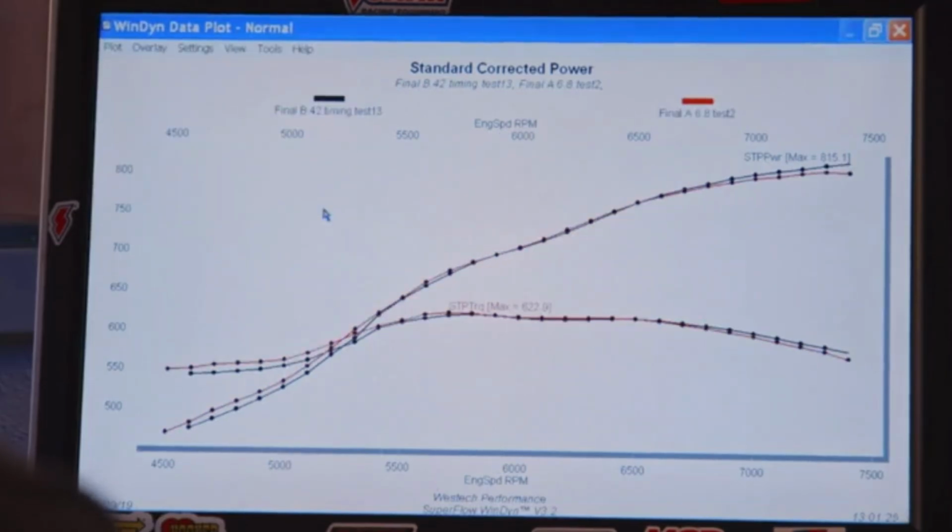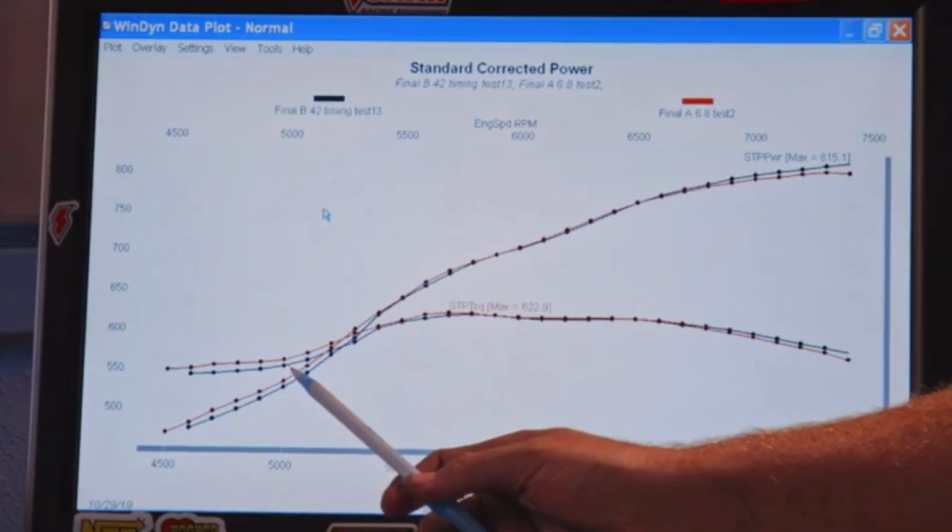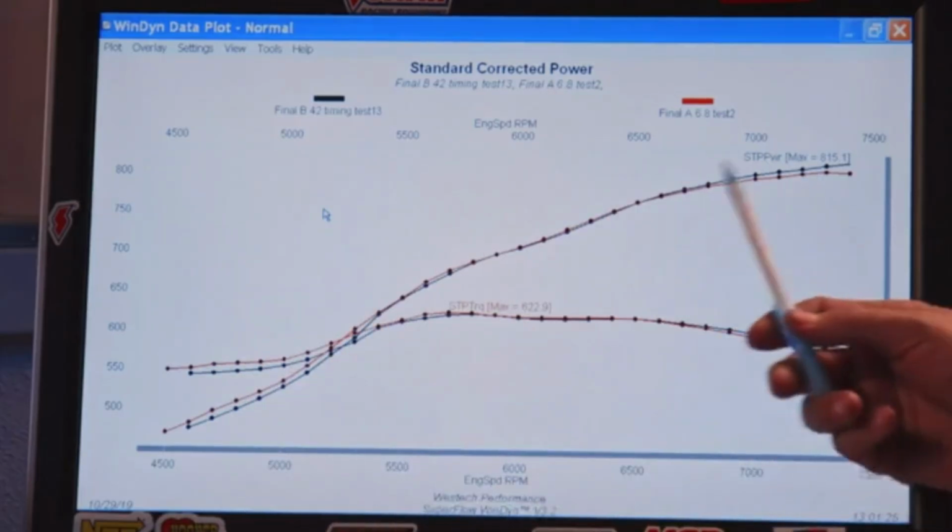Wow, okay, so here are our power curves with the red lines representing the long rod and the black lines representing the short rod. And the short rod ends up throwing away some low-end torque and making some high-end power. Well, you'd expect a long rod to make a little more torque at the very bottom. You would? I would. Because that's the opposite of other theories that I've seen. What everybody else will tell you, or what you read typically now, is that the shorter rod is going to help the port be more active and help bottom end and all that gobbledygook. But you know, you're the guy with the long rod theory. By the same token, if you're going to gain that at the bottom, you're going to give up somewhere else because everything's a trade-off, and you'd expect to see that little edge at the top.